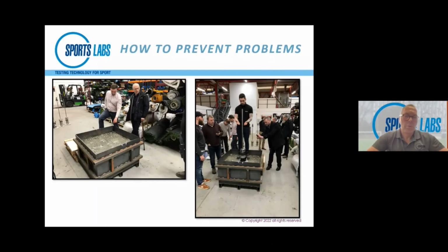So what we've been involved in over the years is trying to look at the science of building bases. This is a scenario where we've created a large mold in the laboratory, and what happens here is we bring sub-base material in and we build the base to the contractor's requirements, and then we'll do all the testing on it. That's a metre square steel mould, and we'll put it in at the layer depths as prescribed, and we'll compact it to the level of